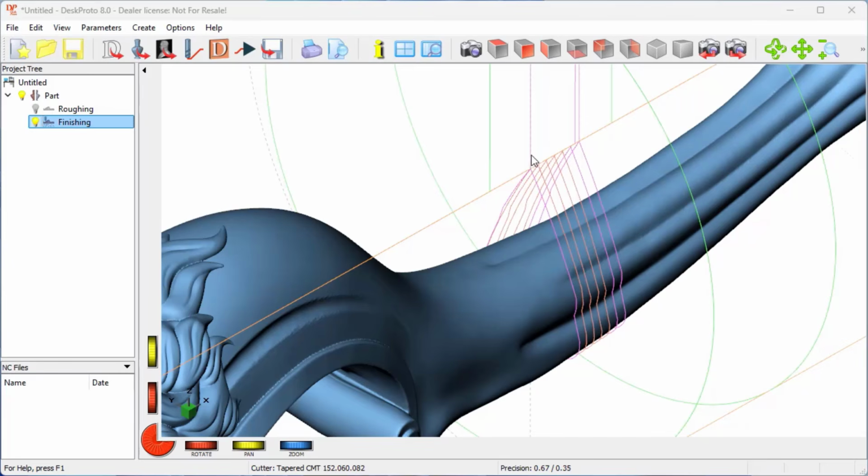And here we are, the toolpath only for a small area. Now you can see what happens. The cutter goes up, goes down, and this part of the surface is simply not machined, so material will remain over there. Why is that?